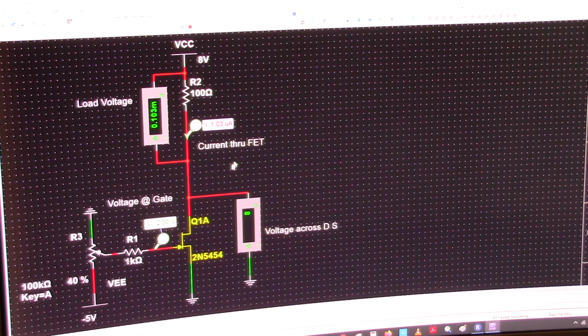You can see how much the current has dropped. I mean, it's almost negligible at this point. Another interesting thing is that you can look at this device and see the 8 volts being dropped across it. So for all practical purposes, it's shut off at this point. If I increase the voltage some more, it'll drop, but it's such a small number now.